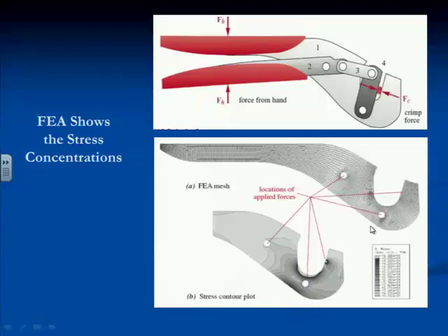analogous to that photoelasticity. So nowadays, they don't do photoelasticity anymore because you can do the same thing with finite element, and it's a lot less work. But the mesh has to be very fine around these holes, otherwise you won't see it. But you can see the concentration right where the crimp is occurring right there, and concentration down here on the bottom of this curved beam. That's in tension, right? And pull this out. This is in bending. And there's a change in contour there, even though it's rather generous.